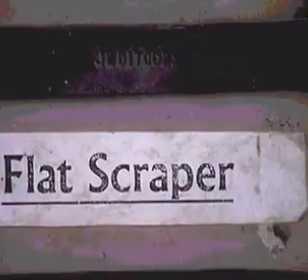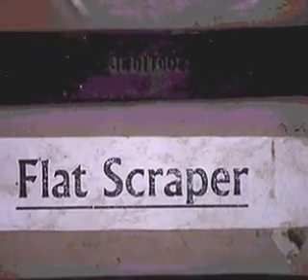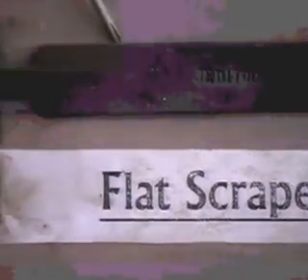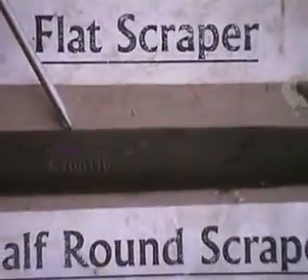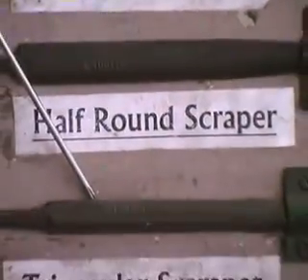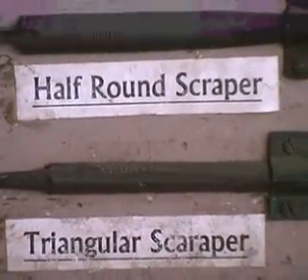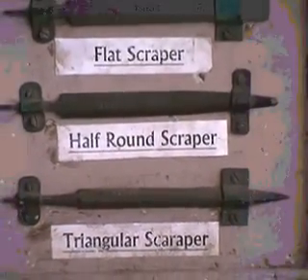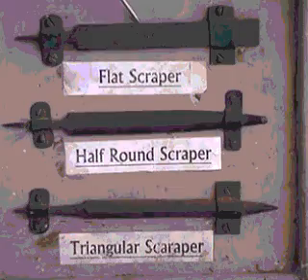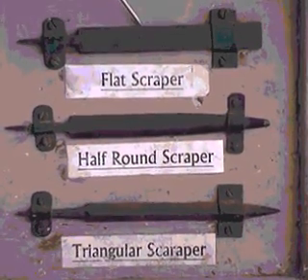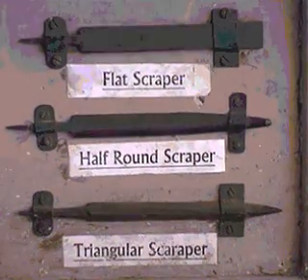There are three types of scrapers: the flat scraper, half round scraper, and the triangular scraper. The material is again the same, high carbon steel, hardened and tempered for all three scrapers.